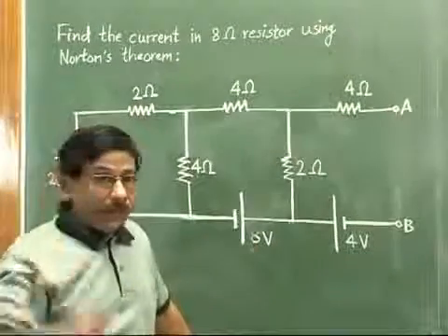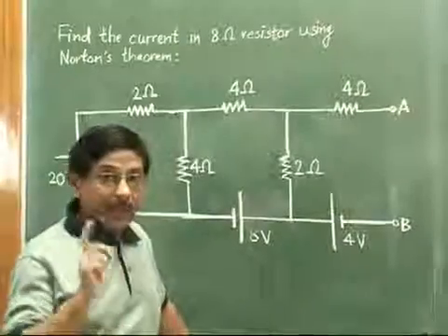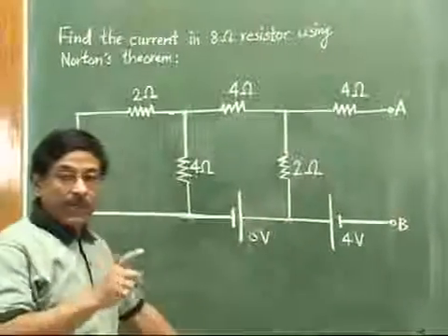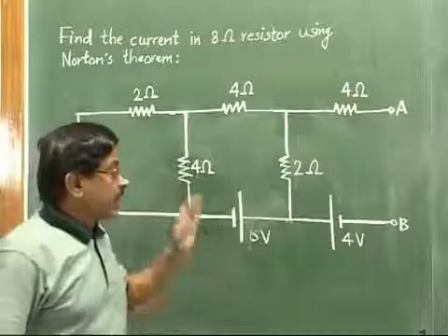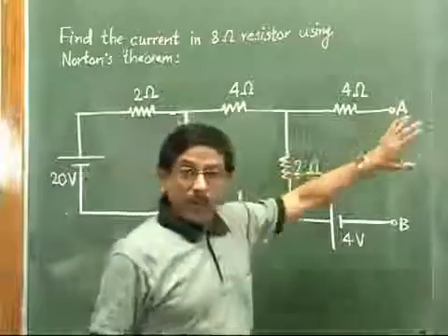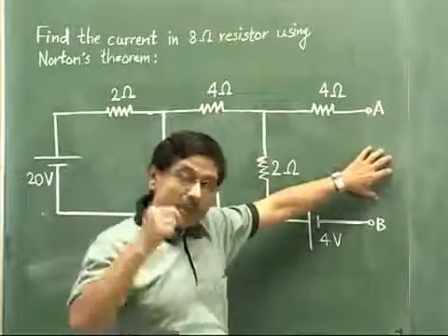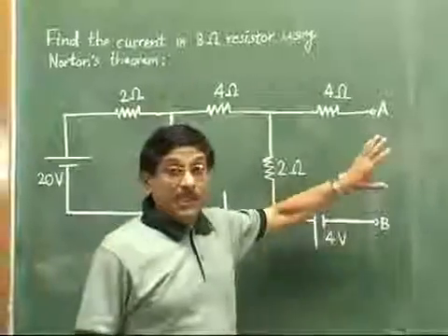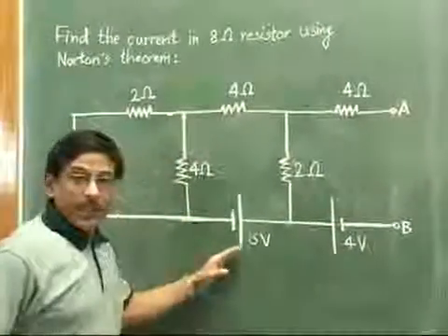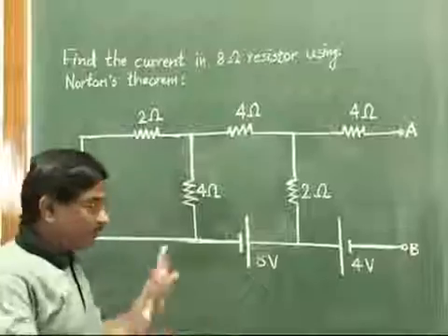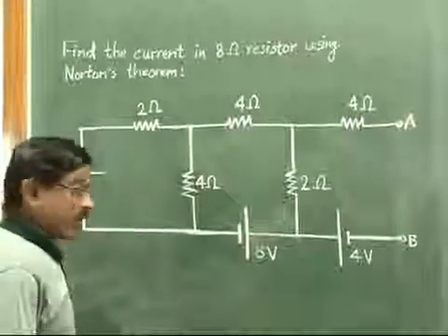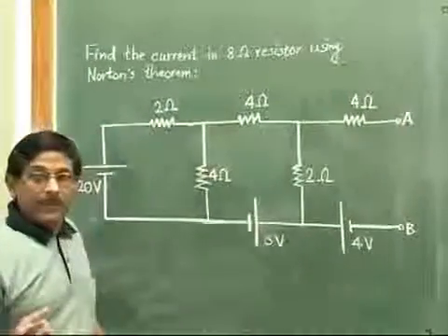Okay. So for finding the value of Rn, Norton's equivalent resistance, we have taken the initial circuit. Which circuit? After removing the load resistor that we want. One more thing is remaining. We want just a passive circuit. That means we don't want the voltage or current sources, or we don't want the power sources in general. What is the basic rule that I have told?